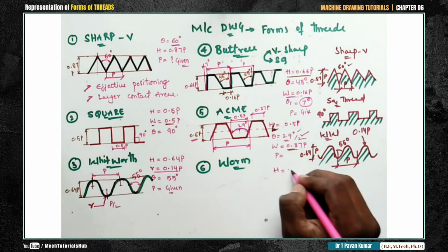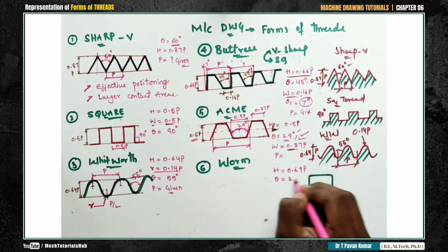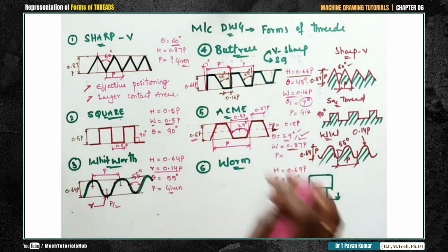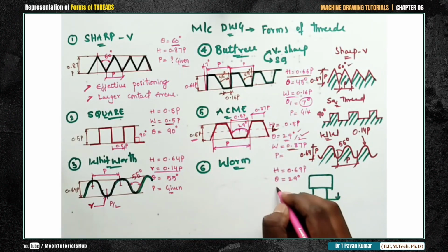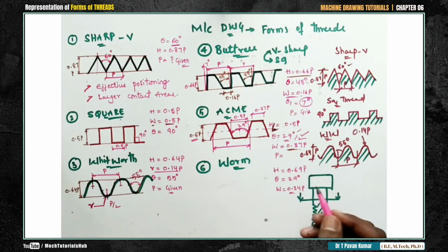What I try to do is, I'll try to draw the baseline by considering the height. I'll draw this baseline by considering the height, which is 0.69 p. I'll draw more locus above. Okay, after drawing this locus, you have to consider width and the height. Height is already shown. What is the width? Okay, width is 0.34 p. I'll make a mark of 0.34 p.